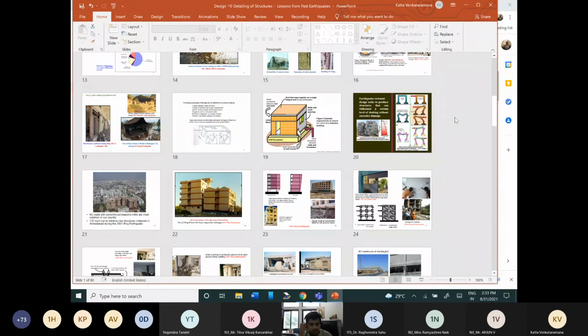And for specific structures like dams which are going to be constructed in a given location, if you have the seismic characteristics of that region, then you can input the earthquake data and do a time history analysis. Thank you, sir. Also, we can incorporate non-linear characteristics of the building better in time history analysis.